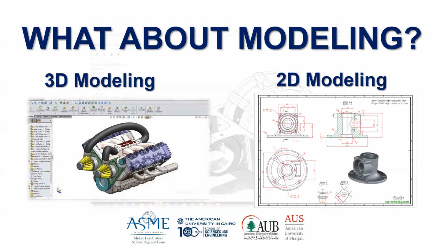And for the working drawing, we have all details for a single part or a single component. So we put all dimensions, we put all GD&T. I'm not sure if you're familiar with GD&T or not. It's geometrical dimensioning and tolerances. So you put everything in the working drawing to illustrate every single detail to the manufacturer of this component. So it's some sort of a contract between the designer and the manufacturer. I'm talking about the working drawing of each component, okay?